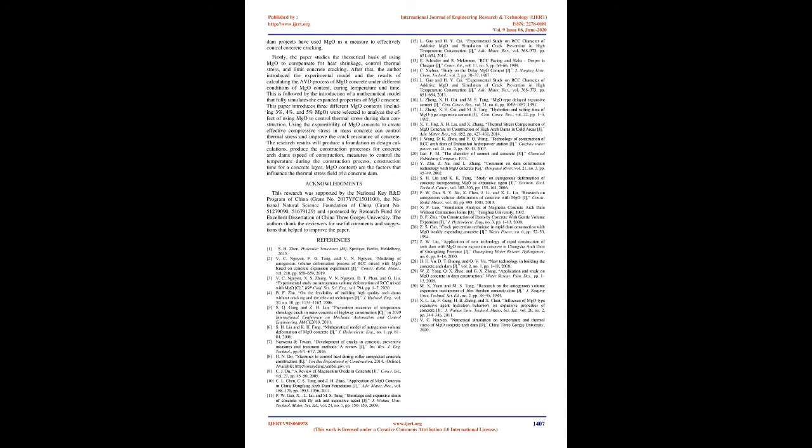The comparison of stresses of the upstream, middle and downstream points of the dam at 52 m of height as follows. Fig. 6. Comparing stress at points at a height of 52 m. Fig. 7. Thermal stress for the point at 80 m of height of the dam. Maximum tensile stress for the point at 80 m of height of the dam are 1.00 MPa, 0.94 MPa, 0.90 MPa, 0.85 MPa, respectively, with concrete mixed with 0%, 3%, 4%, and 5% of MgO content. The occurrence time in February 2022 at the point on the upstream surface of the dam.